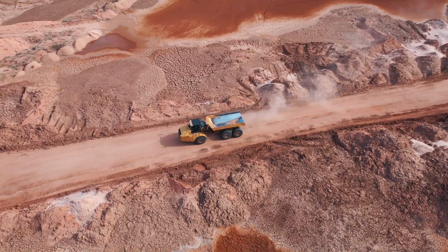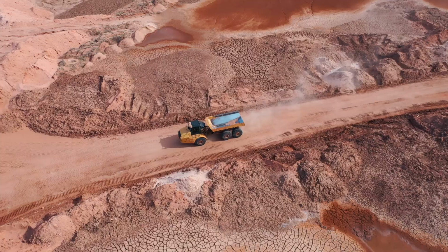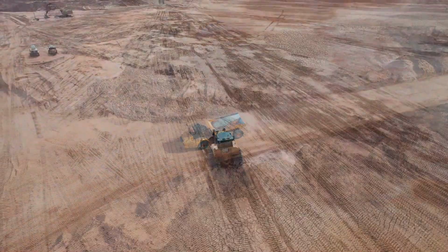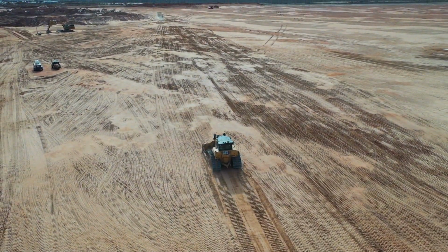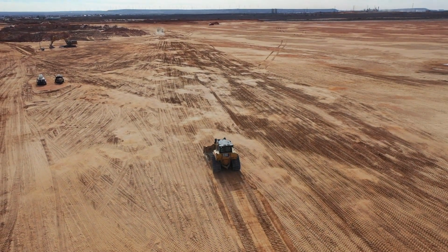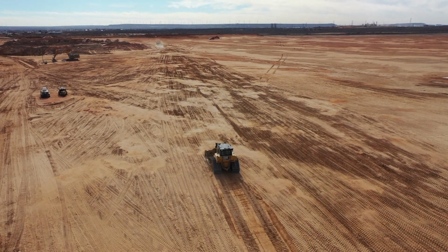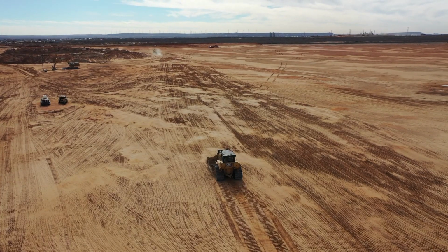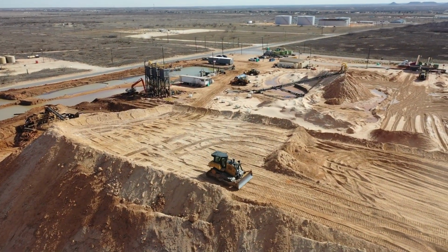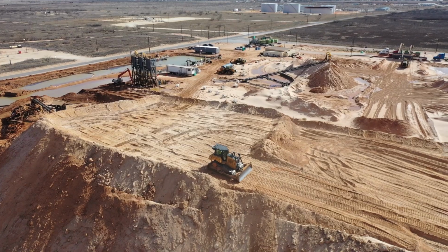Brush piles will be leveled so that harvesting equipment does not get hung up in them. Roads will be made to proper width, with sufficient turnarounds and turnouts. Roads will be kept free of hazards, for example, stumps, rocks, and debris. Keep well back from other working equipment when they are cutting roadways.